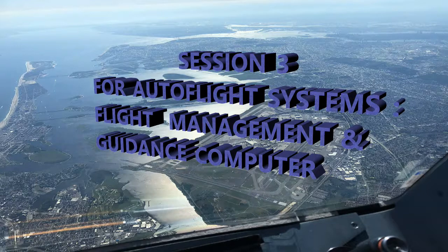So it's going to be doing fault analysis. Typically it's being made on each side, and it's going to be memorizing, storing all this information, whatever it finds. You do have your MCDU BITE, of course. It does the test on the processor, the memory display unit, etc. Your FCU has a BITE. It's going to compute the maintenance status there and send whatever information to the FGCMD. So you do definitely have that.